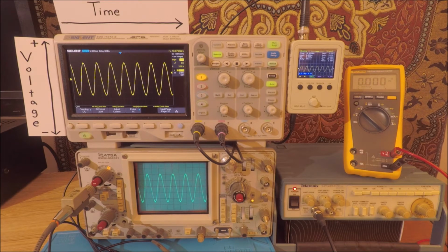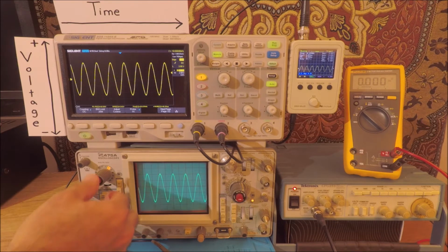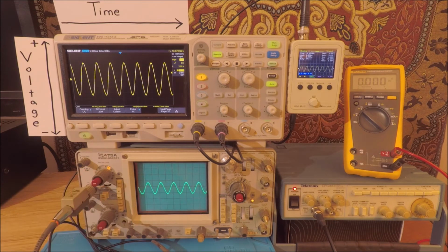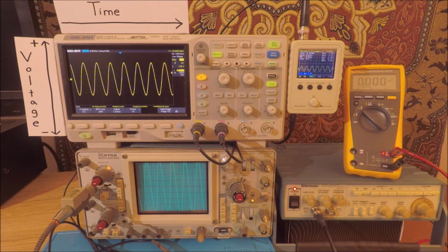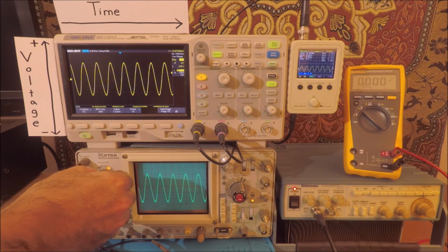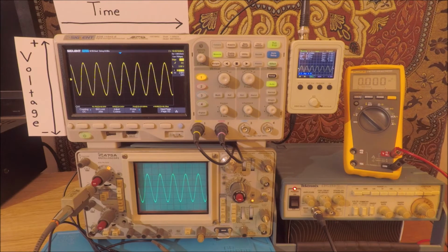If I were to change the scaling on the volts per division, if I were to make it 5 volts per division, then we have zoomed out on that waveform. In fact, we can zoom out even further by changing the vertical scaling. Likewise, we can put it back to 2 volts per division and bring it down to 1 volt per division. So now we're zooming in on the waveform. Of course, now we can't see the full waveform on the screen. So that's the first primary control. You can think of it as the vertical or the y-axis zoom control.